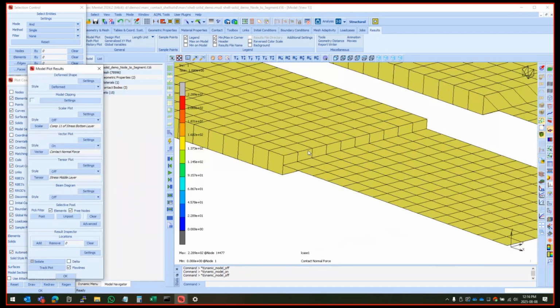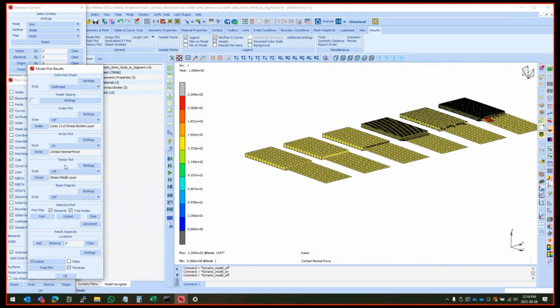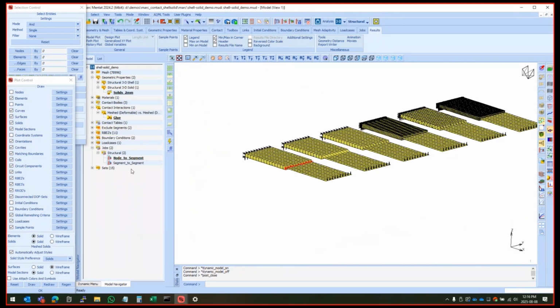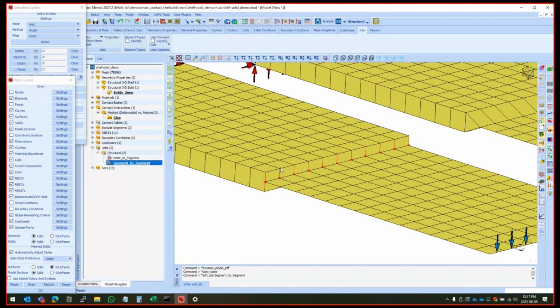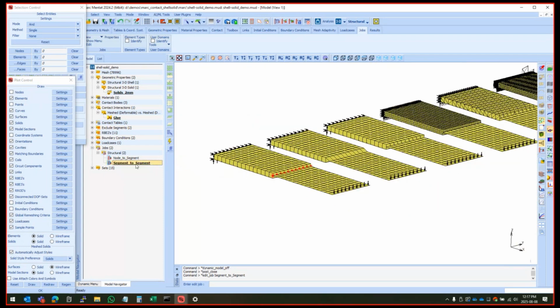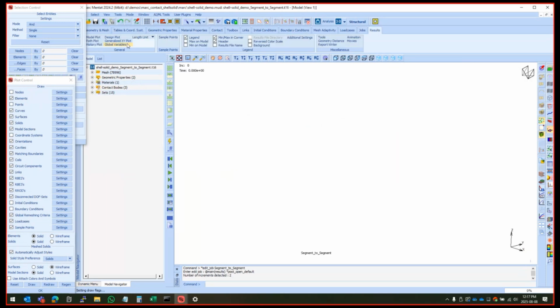If I now go back to the regional model, and all that I do is I change from node to segment. What the purpose of segment to segment is, it's face-based contact. So it picks a series of small points effectively on each face and makes contact. And what it does for shells is that end face there actually has got that same thickness included that we just manually had to add. So just changing to segment in this case, I will rerun it again, it runs relatively quickly.